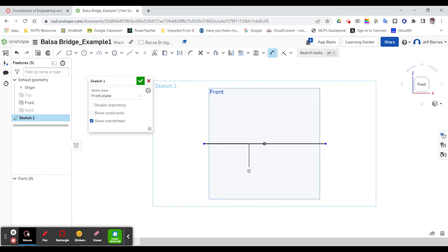and drag down. Try that one more time. Sorry about that. You really got to make sure you select the point and not the line. That's what I did wrong. And so I'll click and then I'll make it 5 inches and hit enter. Then I'm going to do the other endpoint. And then again, making sure I'm selecting the origin point, not the line, and drag down. Okay, so now my total is 10, 5 and 5 is 10.